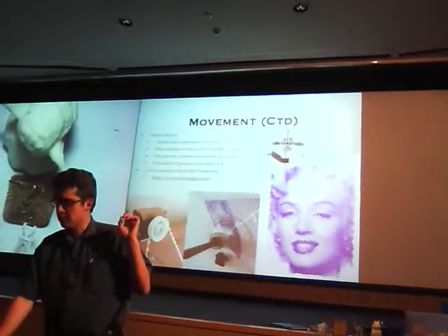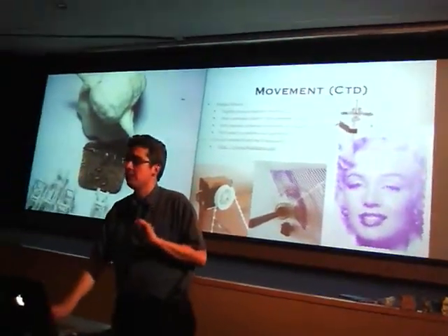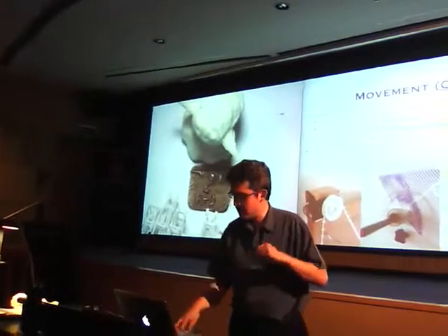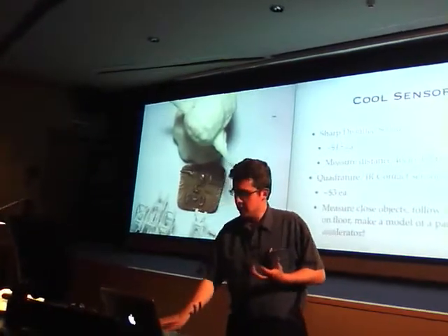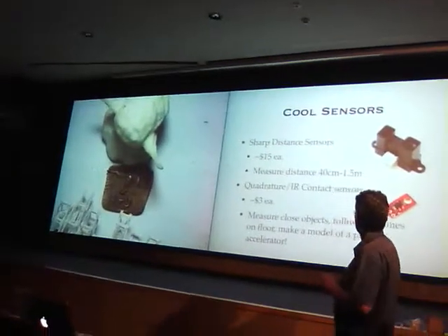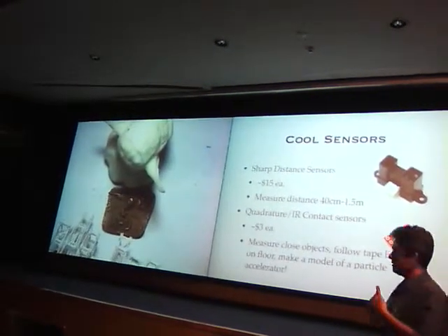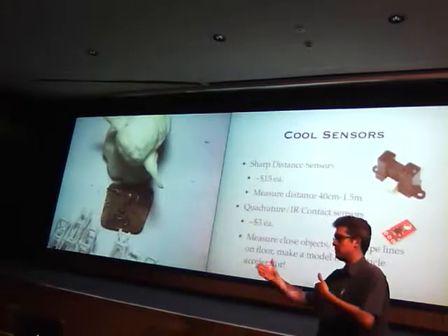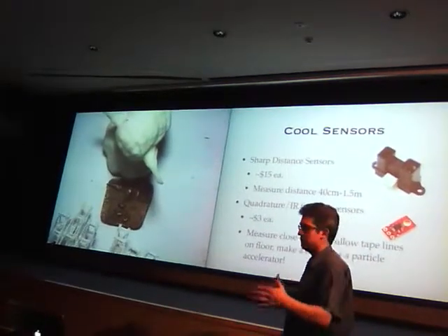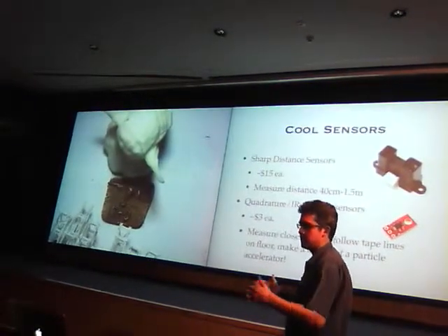There's also a couple of cool open source polar graphs you can download and modify or create your own. Getting data from sensors. A cool way, these guys up top right, sharp distance sensor, you can measure analog voltage based on the distance to an object. I have robots that use these things to avoid hitting walls, and they're really cheap, simple, and easy to use.